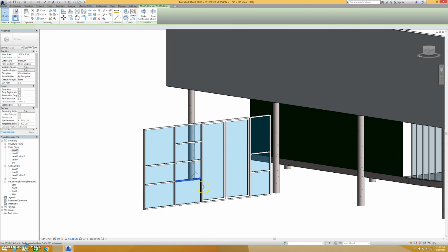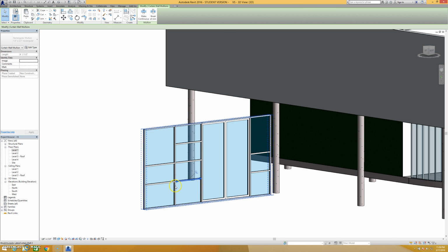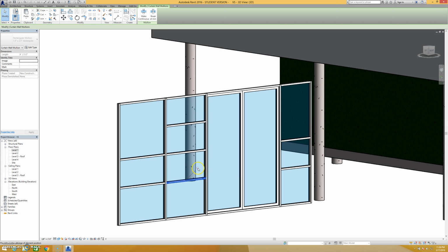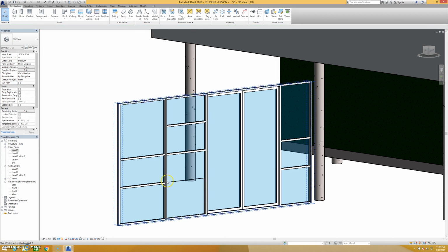And so if you want to delete a mullion, for instance, to just expose the glass, like in this case it's pinned, I had to unpin it. So I can do that with the hotkey P in, or just by clicking the pin icon, and then I can remove it, and I've got just my joint.